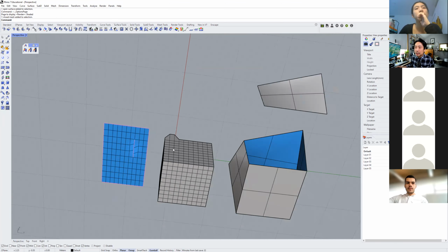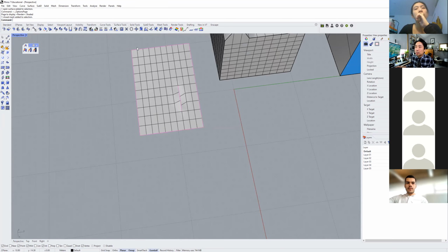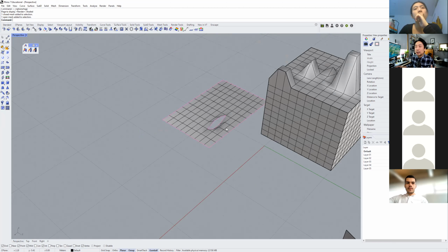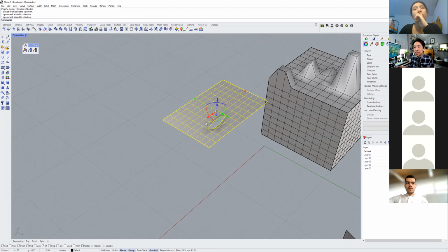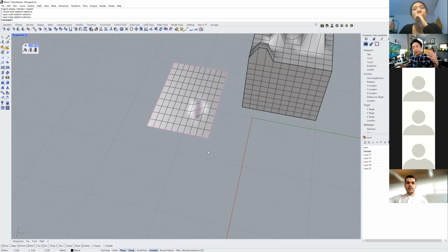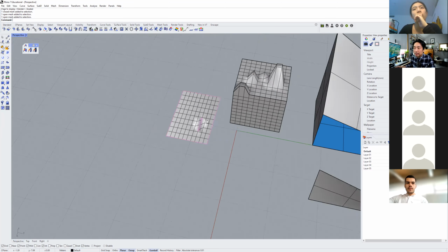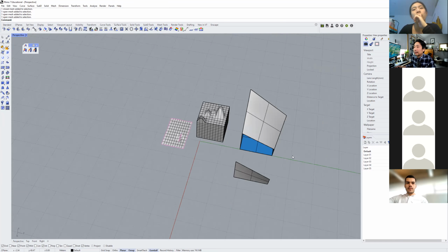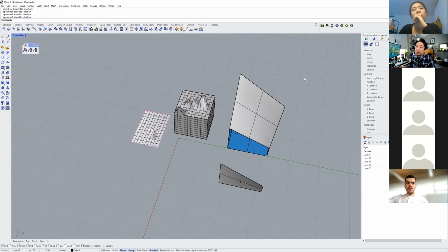So that makes me aware that this is a watertight object. This shows no signs of naked edges. This one, there are naked edges everywhere. So I need to be aware that something is wrong with this geometry. This cannot be 3D printed, or whatever I want to do with it. So this will give me problems down the line, okay? So with that setting, I have a lot of what I need to move forward.